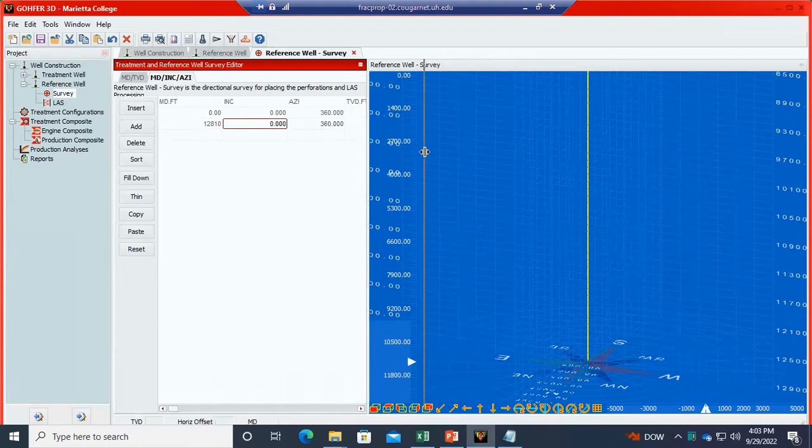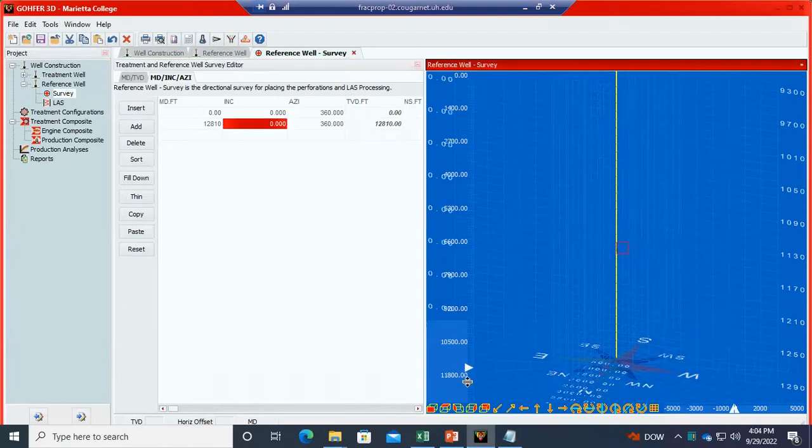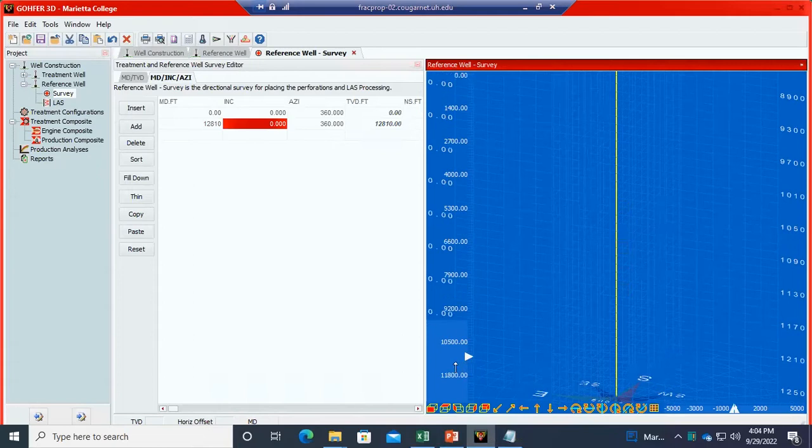So there are no great differences between the MD and the TVD. Then we need to define our log to create geomechanical parameters. The geomechanical parameters that we need for hydraulic fracturing are mainly the Young's modulus, and specifically the static Young's modulus, the Poisson ratio, the minimum horizontal stress, and toughness data, or the tip propagation data.